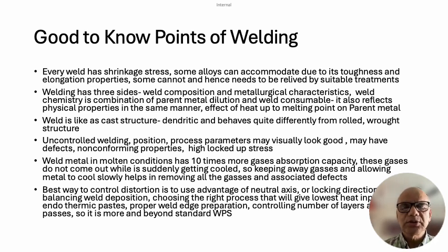Such porosities or inclusions may be a trap for hydrogen to get collected, and once this hydrogen, which is the finest particle, gets accumulated there, the pressure keeps on rising in that cavity, and that leads to a very high stress concentration at microscopic level and creates a notch.